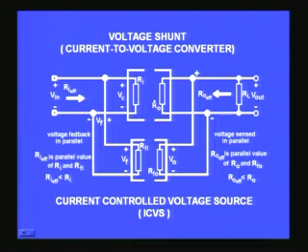You will see the effect of that on the input and output resistance of your amplifier. This block at the center is the amplifier. So you can see what is going to happen. If you look from the output side, the Thevenin's resistance of the amplifier and the output resistance of the feedback network will come in parallel. When I look from here, this and this will come in parallel, and when 2 resistors are in parallel, you know what the effect is. The effect is to reduce the effective resistance, and therefore the effect of this feedback arrangement on the output resistance is to decrease the resistance.